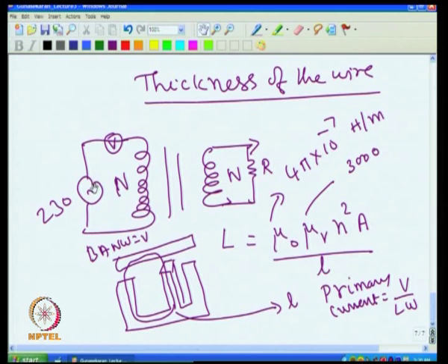So the net result is, when I load this, you will have magnetic field cancellation, and then to get back to the original field, more current now goes through the primary. Other way around, if I load the secondary more, I will find more current flowing in the primary also. So the primary current consists of two currents.